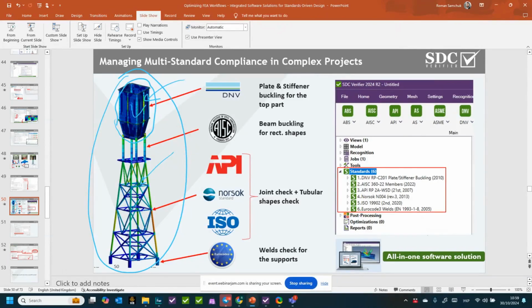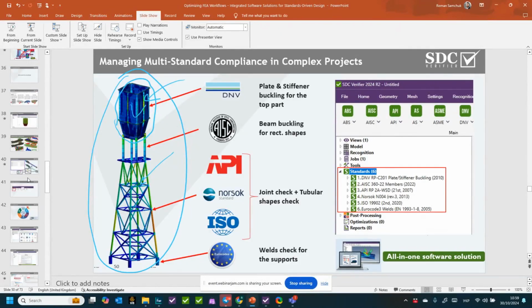Another one: I also noticed a tab for hotspot stresses in your short video about the welds. Are the stresses directly accounted for in the standards? Yes, they are accounted for in the standards as well. As you know, many standards are based on the nominal stress method calculation, for example, like fatigue, but more advanced standards like Eurocode or IIW prescribe hotspot stresses. So hotspot stress is an optional case, so you have a checkbox whether you want to continue using the nominal stress method or the hotspot stress method. So this is all accounted for.